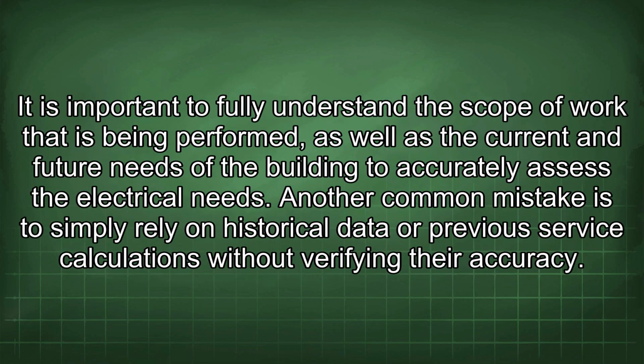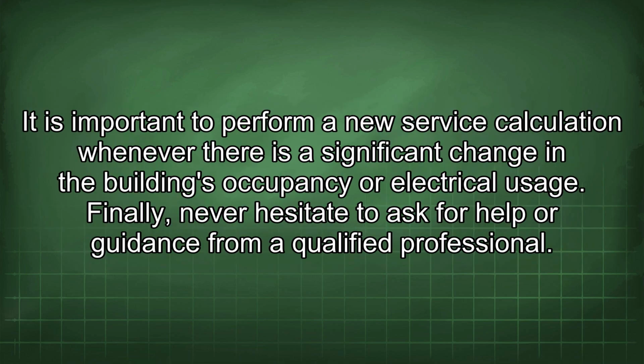It is important to fully understand the scope of work that is being performed, as well as the current and future needs of the building to accurately assess the electrical needs. Another common mistake is to simply rely on historical data or previous service calculations without verifying their accuracy. It is important to perform a new service calculation whenever there is a significant change in the building's occupancy or electrical usage. Finally, never hesitate to ask for help or guidance from a qualified professional.